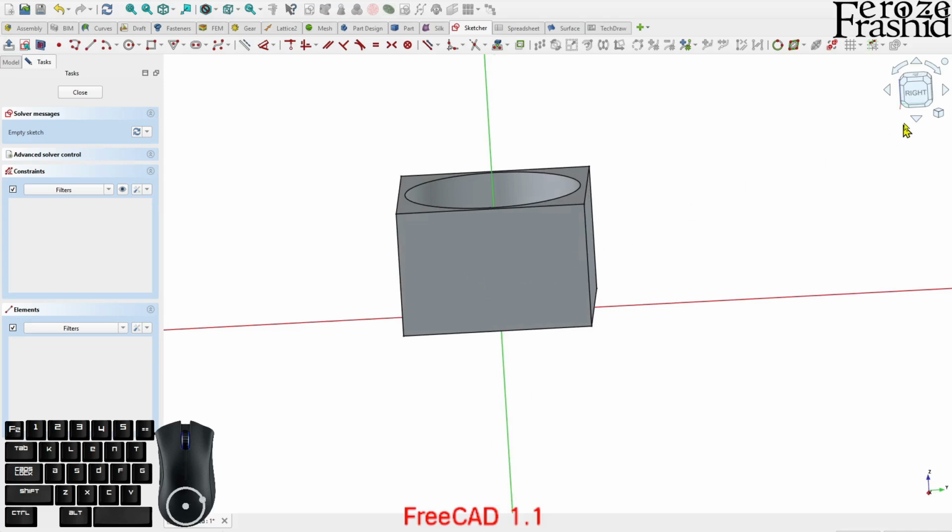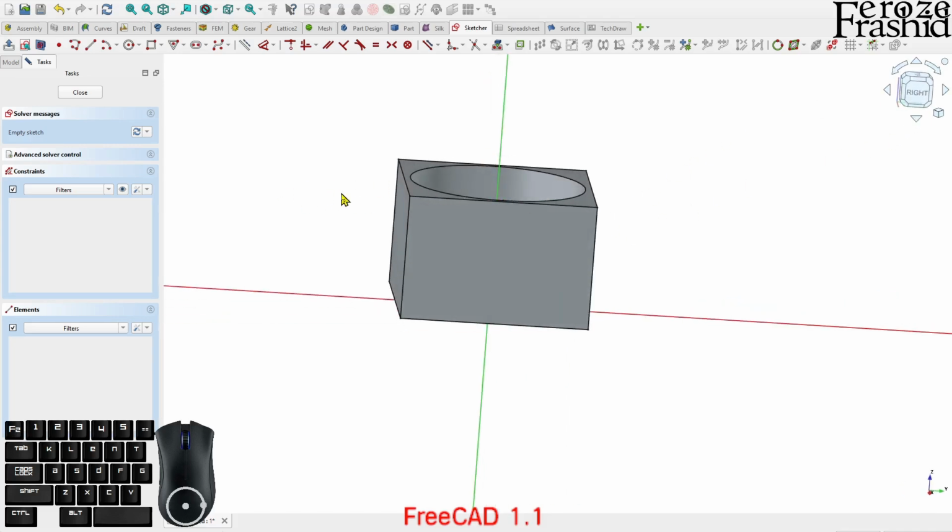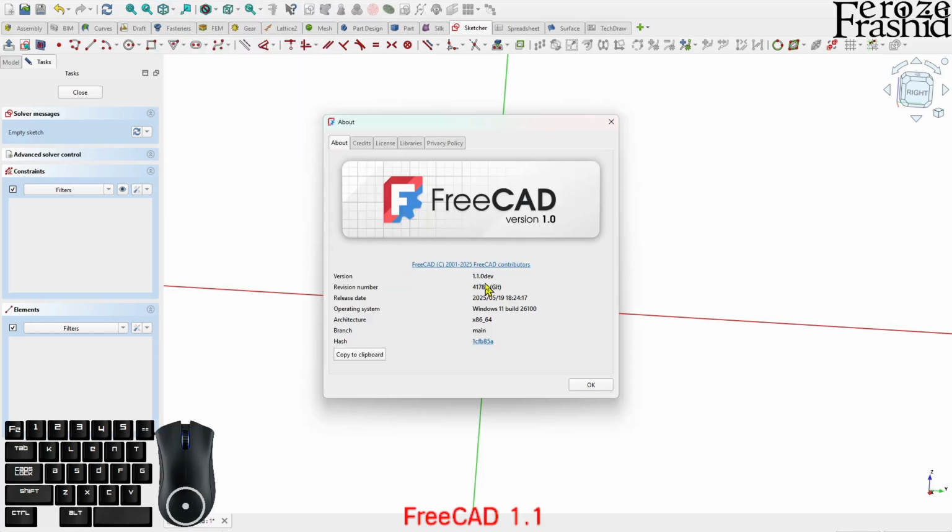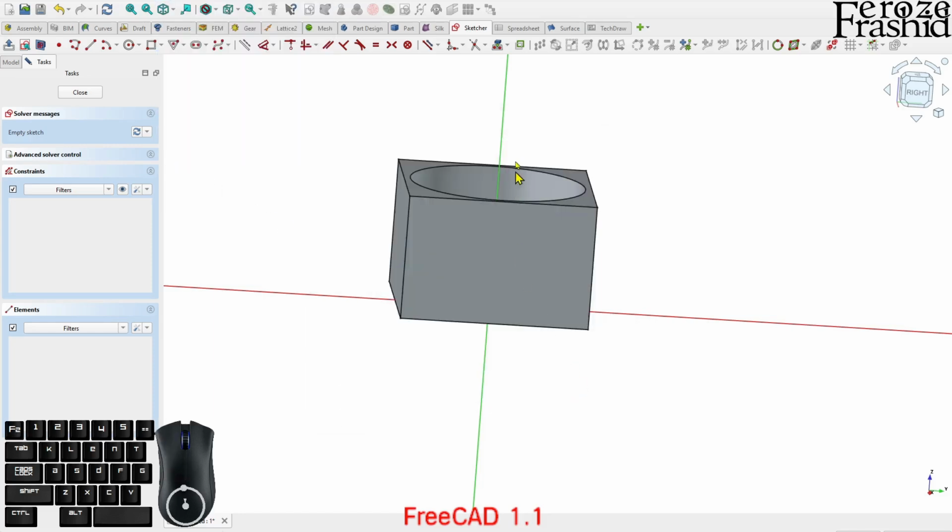All right, on this one I want to draw that on this side, on the left side. So I want to pull in this geometry. I am using the FreeCAD 1.1 developer version. I say that because this external geometry is different between FreeCAD 1.1 and the stable 1.0.1 version. In here, the external geometry will pull in construction geometry if you have it as construction. For this case, it will pull in the solid geometry. So I want to transfer it to construction and pull in this point.